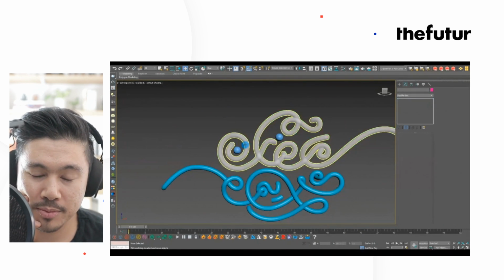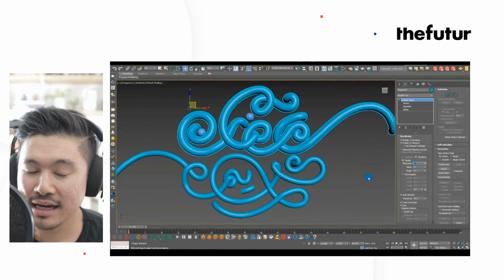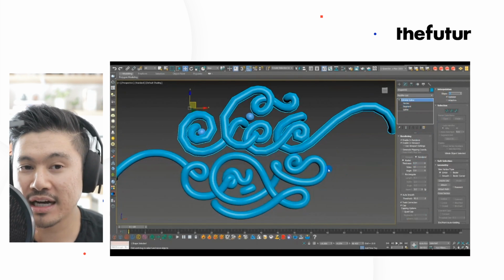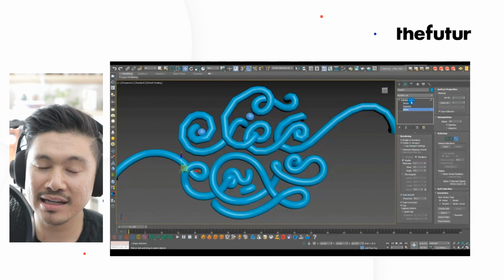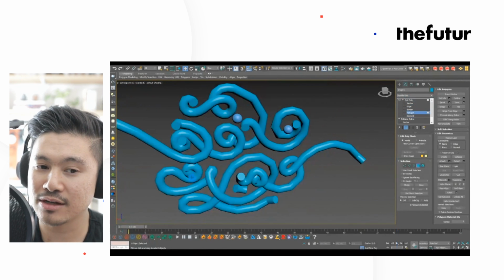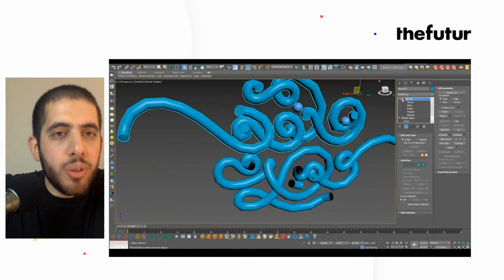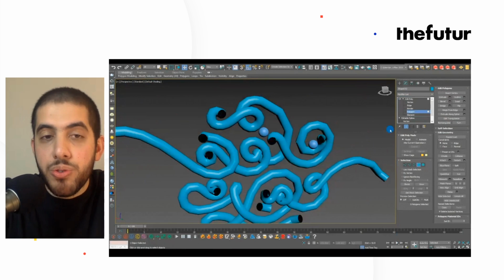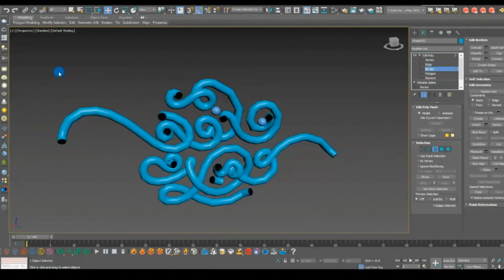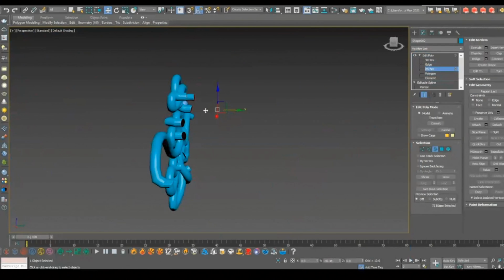And just for those people who are asking, this is in 3D Studio Max. You started in Adobe Illustrator, brought the paths in here, and then you got a circle, and you just wrapped it around this spline that you had to make the tube, and then you started cleaning it up, giving depth so the geometry is not overlapping each other, and then you're extending the ends now so it feels like it's going to plug into a wall or a fixture. Exactly. And I'm intentionally trying not to use any 3D terms because I know some people don't use 3D and some people use different programs, so I just want to keep it super generic. So even though I use 3D Max, I'm intentionally not getting into the specific name of the tool so everybody can benefit from it.